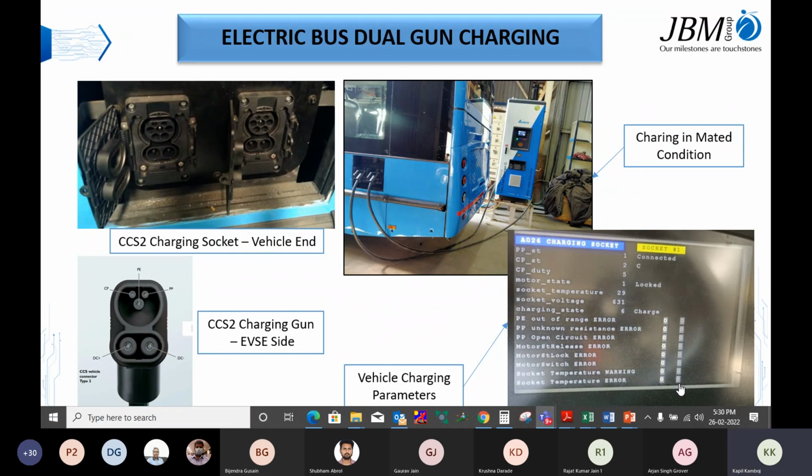Okay, got it. If you remember, in the PDU, in charging, we have used 4 contactors, positive and negative. That is also controlled by BMS, because we have a CC, or you can say a bus issue as well, separately, which is also controlling that. So that is a complete protocol, Arjun. I cannot define it in a small presentation right now, but that is an SAE standard. Okay, got it, sir. Continue.